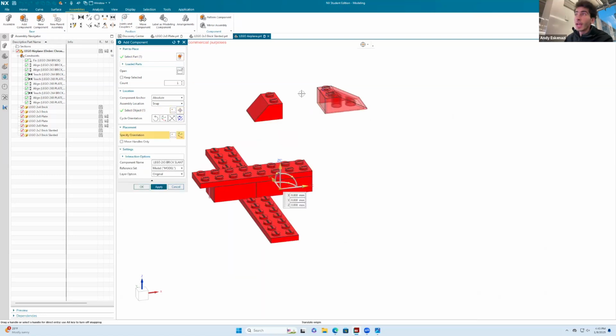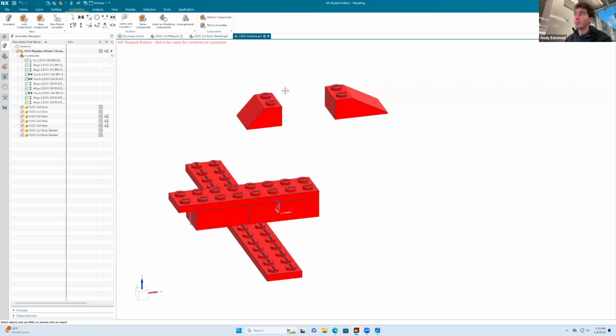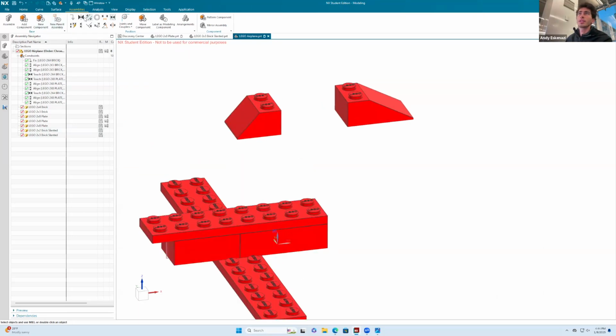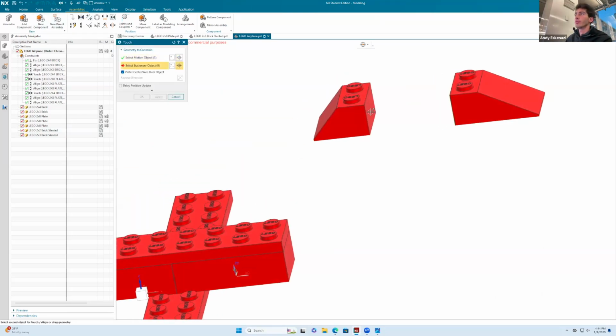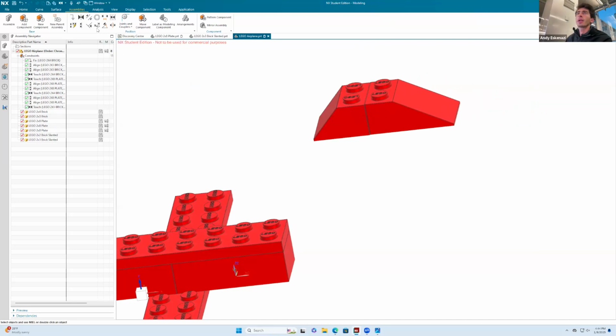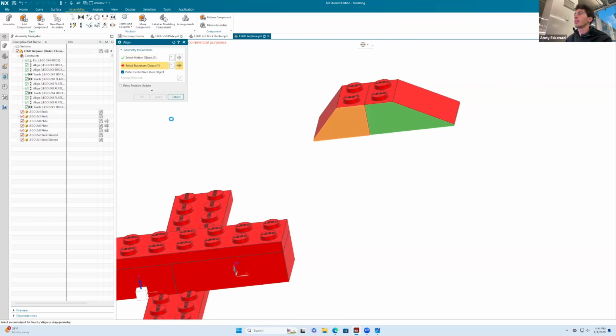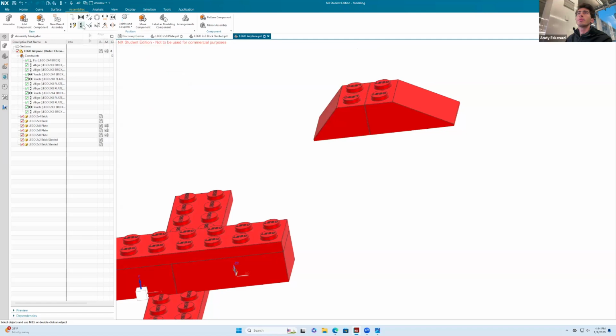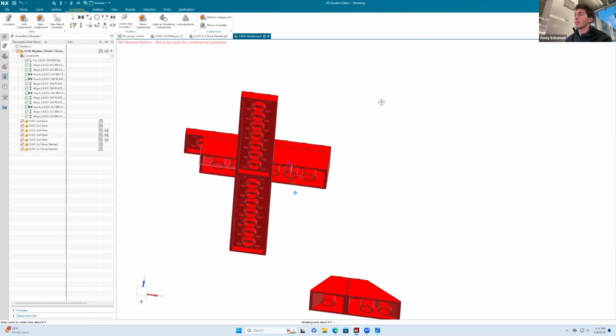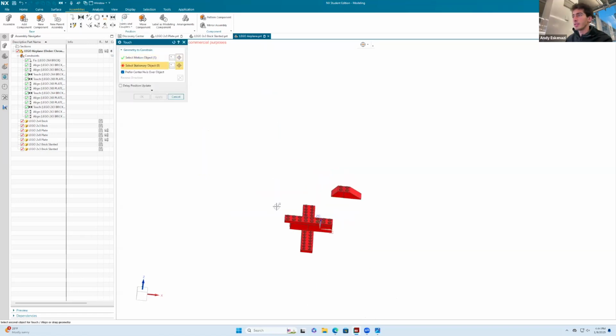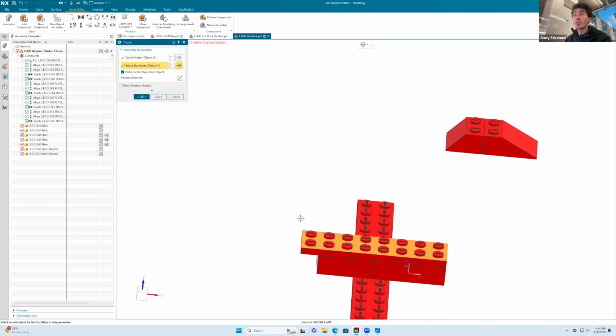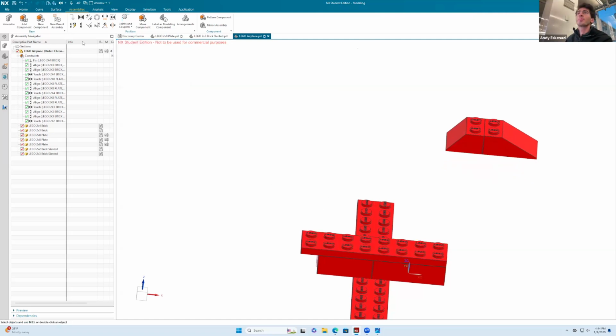Take positioning here. And in fact, look at what we're going to do. We can build a little sub-assembly in here. I can say, all right, you go off to touch right there, and then I'm going to align these two faces. I'm going to align these two like this. And then I want this face to be touching this face. So now it's going to move everything at the same time.